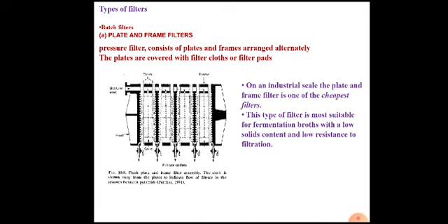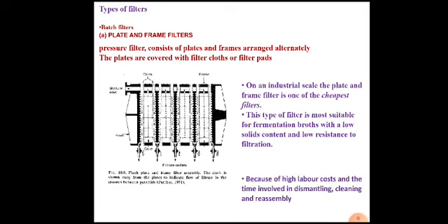It has low resistance to filtration, but it is highly laborious because of high labor cost. Cleaning is difficult, and dismantling, cleaning of the plate filters and assembling is a time consuming process. But nowadays we have advanced technology in which plate frame filters can work continuously, which we'll see in the next slide.